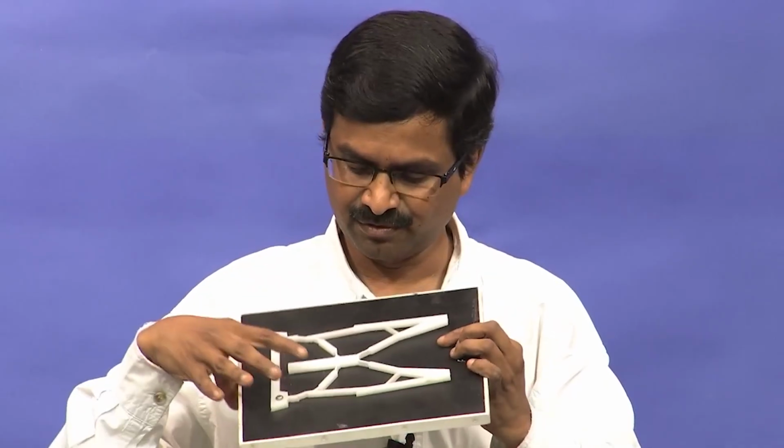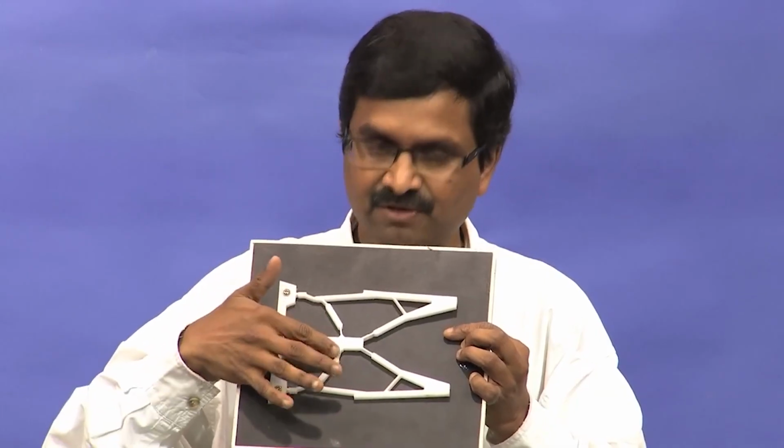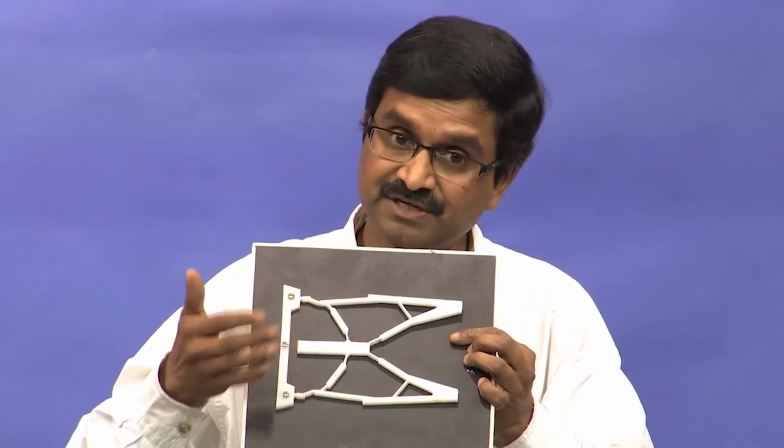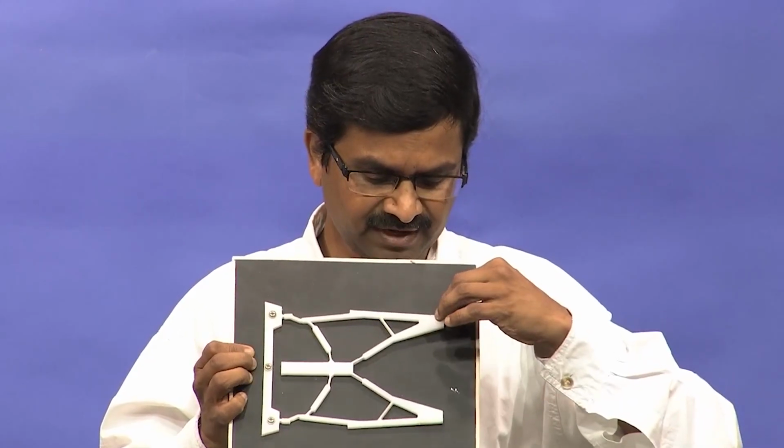In fact, if you were to look closely here, they already undergo some plastic deformation. In fact, the color of this polypropylene changes, becomes more whitish, indicating that it has undergone plastic deformation. Sometimes they are called plastic hinges as well, not because they are made of plastic materials, but because they have undergone plastic deformation, and in fact their stiffness also changes a little bit.